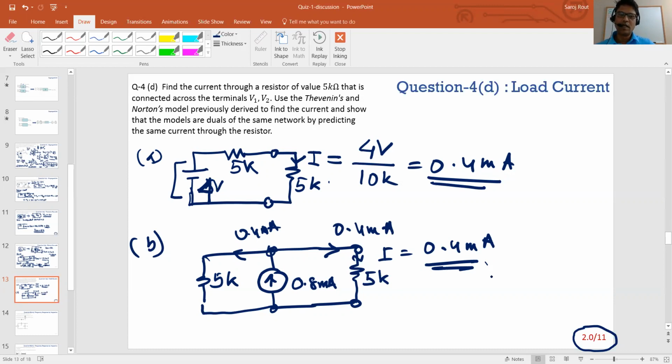So you can use one against the other, and for some circuits you would like to use the current source. For example, if you have a low impedance node going in, then you would like to use the Norton equivalent because it's easier to calculate. Whereas if you have a high impedance node like an op amp, you want to use the Thevenin equivalent because it's easier to calculate that, right? All right.